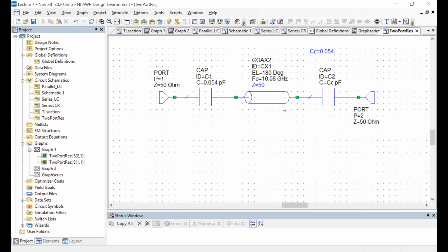So this technique is very generic, but in this context, when you have a two-port system like this, for the simplest case, you want to monitor only one of the ports. If you're injecting a signal, say from port 1, you would ideally monitor only port 2, where the signal is coming out, and not worry about what is coming out of port 1.